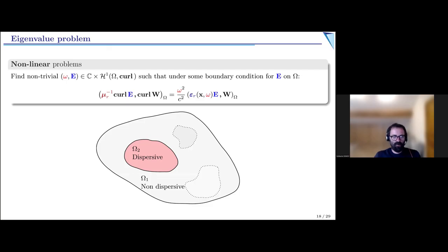So now we are also able to solve non-linear eigenvalue problems in GetDP. In photonics, in nanophotonics, the non-linearity occurs most of the time because we have dispersive materials, and the dispersion is most of the time in epsilon, the permittivity. Mu is considered non-dispersive in this case because we want to take care of materials like gold, silicon, etc., which are amagnetic, so mu is 1.